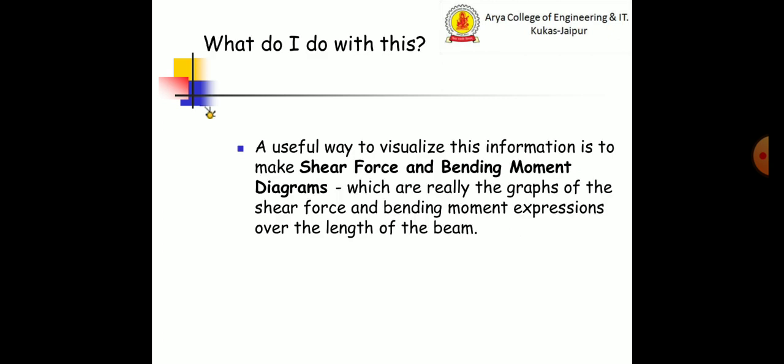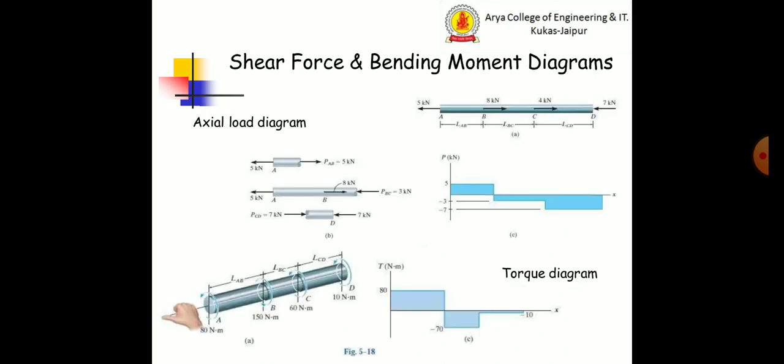A useful way to visualize this information is to make shear force and bending moment diagrams, which are really the graph of the shear force and bending moment expressions over the length of the beam. Shear force and bending moment diagrams, here axial load diagrams.